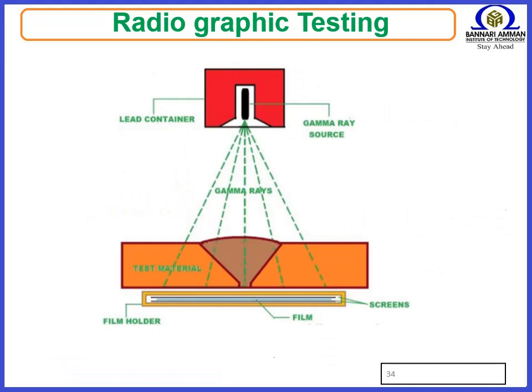Digital radiography, DR, digitizes the radiation that passes through an object directly into an image that can be displayed on a computer monitor. The three principal technologies used in direct digital imaging are amorphous silicon, charge-coupled devices, CCDs, and complementary metal oxide semiconductors, CMOSs.